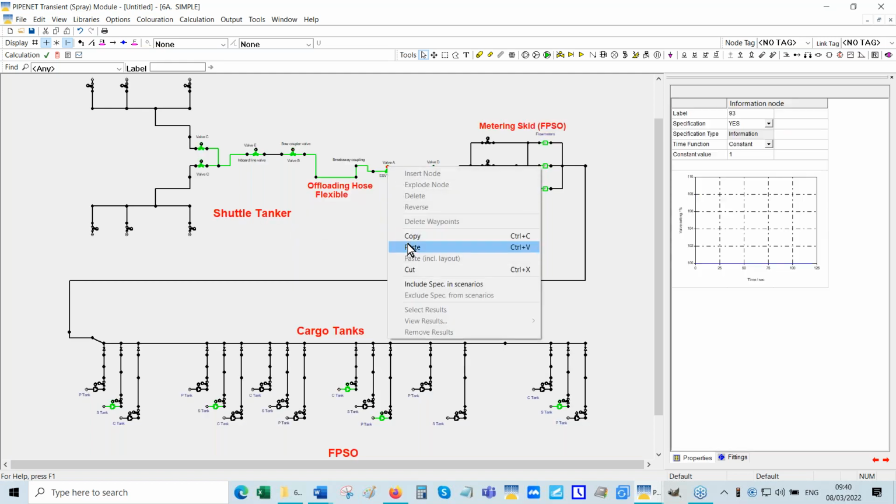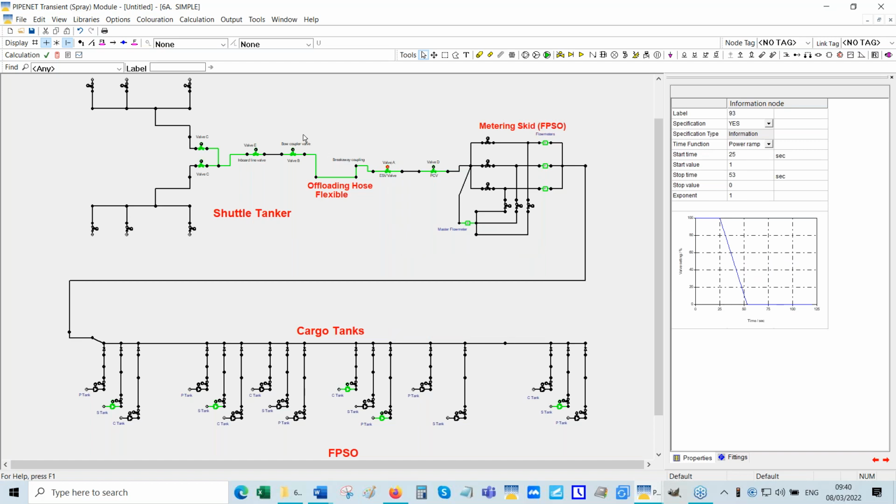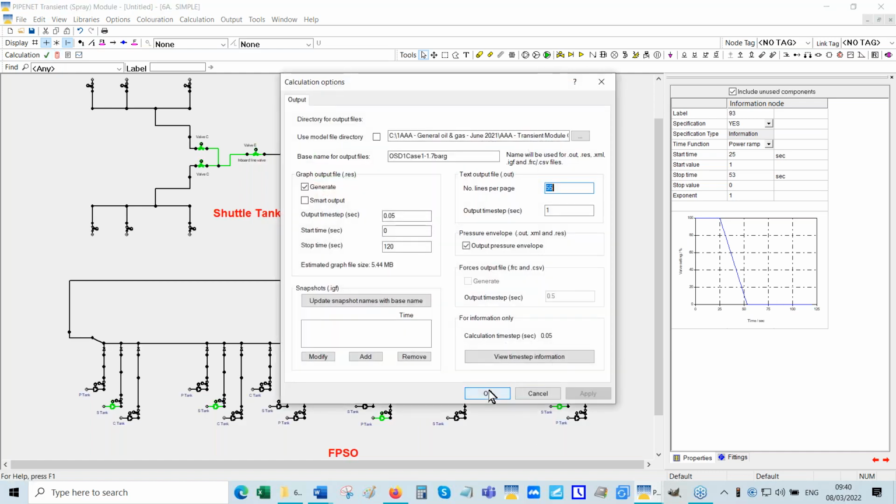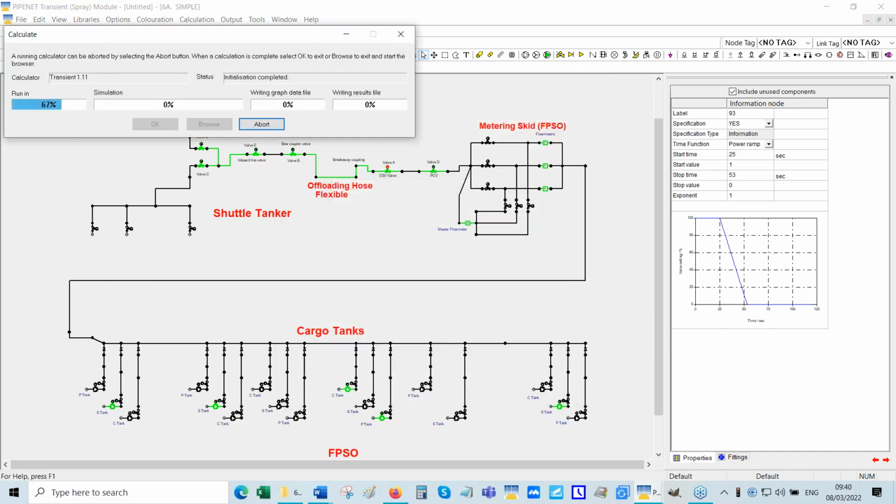It came up with a very, very simple idea. This goes 3 valves rather than just 1 valve. The idea is that if we just close the 1 valve, it bears the brunt of the flow rate. If you close 2 other valves, the inlet pressure coming to this valve is already decreased by the other valves closing.